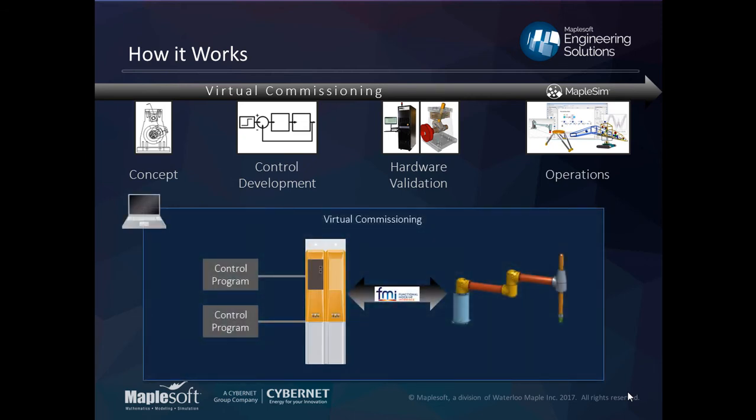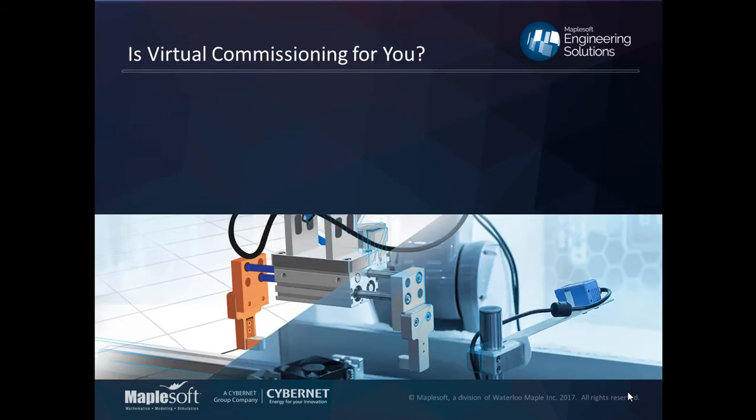And to show it in just a graphical way, on the right there we've got our model, our digital twin. Using this increasingly popular standard called the Functional Mock-up Interface, that's how we bring that model into popular automation software. And when we can bring that model inside, now we're able to bring everything together in one piece of software to do that kind of testing. So that's really been a key technology that's been responsible for the growth of virtual commissioning.